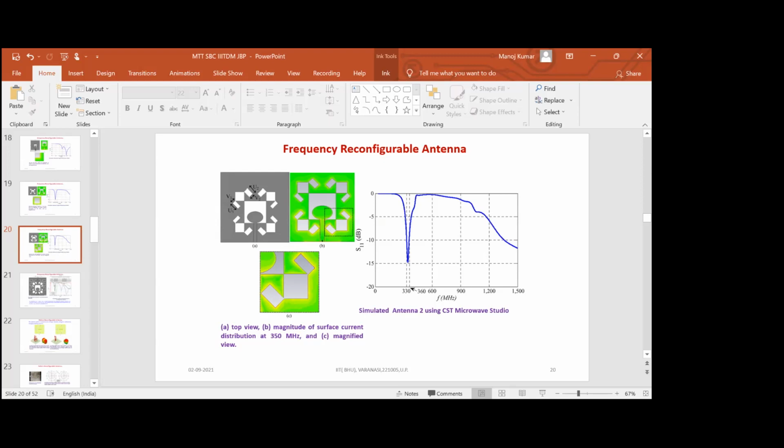When you are designing for millimeter wave, another challenging task is the biasing circuit. The biasing circuit is always challenging at any frequency, lower or higher. So you should be very, very careful that it does not affect your radiation characteristics, because in the millimeter range your radiating components are very, very tiny and your biasing circuit would be bigger than that, so it will affect. So you can design the biasing circuit in chip form. That would be better.